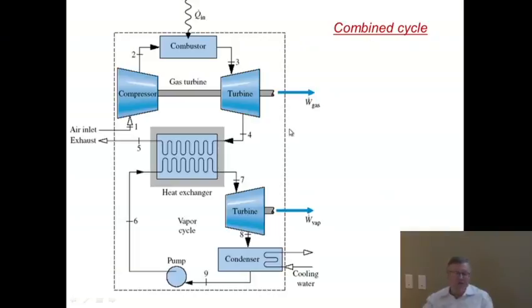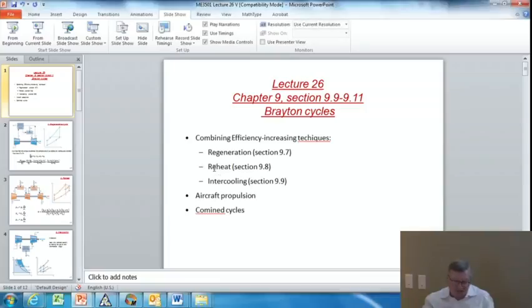Let's say, now that we look back at power production, the most modern power plants that are gas-fired use a combined cycle. So we combine chapter 9 and chapter 8. Remember, the Rankine cycle looked something like this. You had water as a circulating fluid between 7, 8, 9, 6, and 7. Your water went through a turbine, so this is now a vapor turbine, went through the condenser where you make water back up. The water is pumped back up to the high pressure in the pump, and then goes through a boiler or a steam generator.